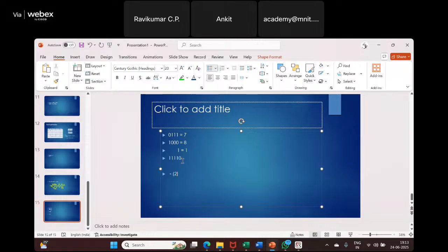Another way to write the same thing will be, you treat this as an unsigned number if you want. This 1110, we could treat this as a 4-bit unsigned number. So that will make it 14. 1110 is 14. But because it's a negative number, we can have a negative weight of minus 16 for this. So minus 16 plus 14 is also minus 2. So it's up to you how you want to do this.